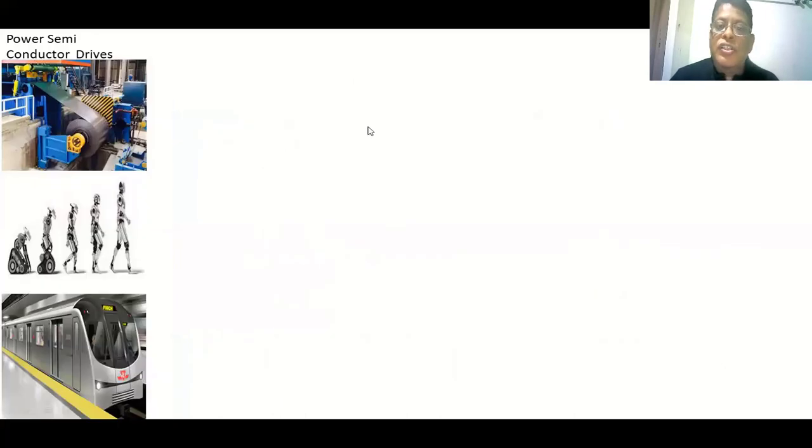We're going to summarize this class. In this class, we have discussed the fundamental equation for the torque in any electric drive. Next, we have seen the different components of the friction torque. Next, we have seen the windage torque. We have discussed the different load torques available practically. In load torques, we have observed the low speed hoist, high speed hoist, traction, and fans, compressors and propellers. Finally, we have observed the coil driver. The power taken by the coil driver is constant, so we call this drive a constant power drive also.